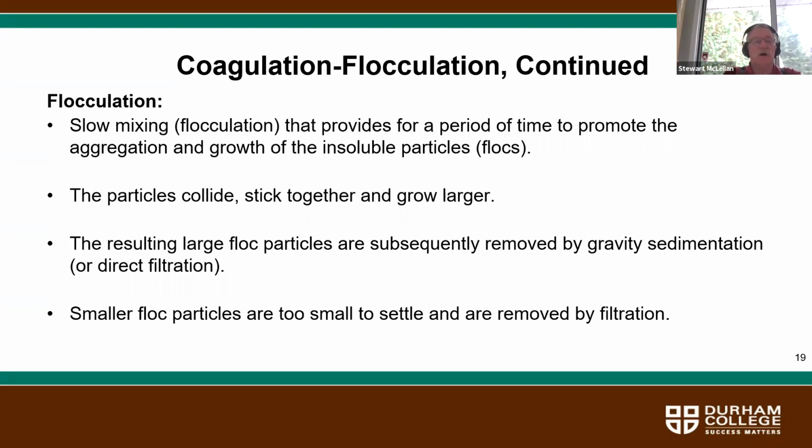So once you have those large flocs generated, they can be settled out of the water through gravity sedimentation. They can be passed through some type of filtration media, or as in the case with industrial wastewater treatment facilities, where space is at a premium, they will use what are called lamella clarifiers.